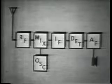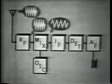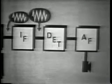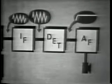But will a conventional receiver receive this different kind of signal? Let's look at a typical AM receiver and see. The incoming sideband signal is RF. Now, RF amplifiers, of course, will receive this signal and amplify it, and it can be mixed to produce an IF signal. The IF signal will be amplified as usual. But what happens at the detector? You recall what a detector does? It rectifies and filters the IF signal and detects the amplitude variations. But in a single sideband signal, modulated with a constant tone, the single sideband would have constant amplitude. The detector would rectify it, filter it, and out would come pure DC. No intelligence. So what must be done?